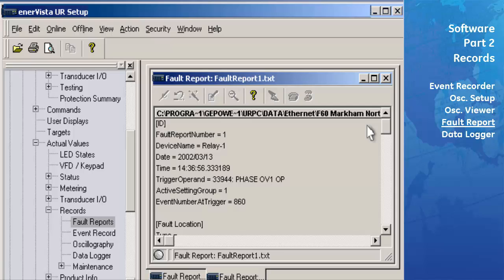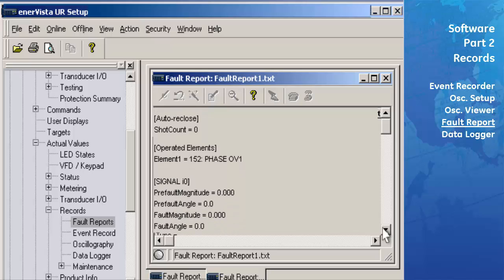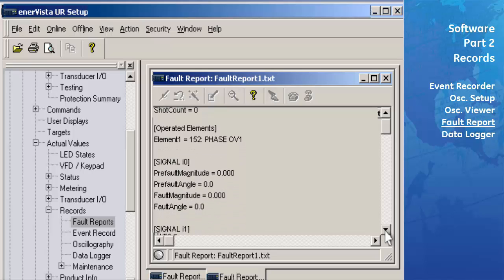trigger. The captured data also includes the fault type and the distance to the fault location, as well as the reclose shot number in line and distribution relays. The trigger can be any flex logic operand, but in most applications it is expected to be the same operand, usually a virtual output, that is used to drive an output relay to trip a breaker.